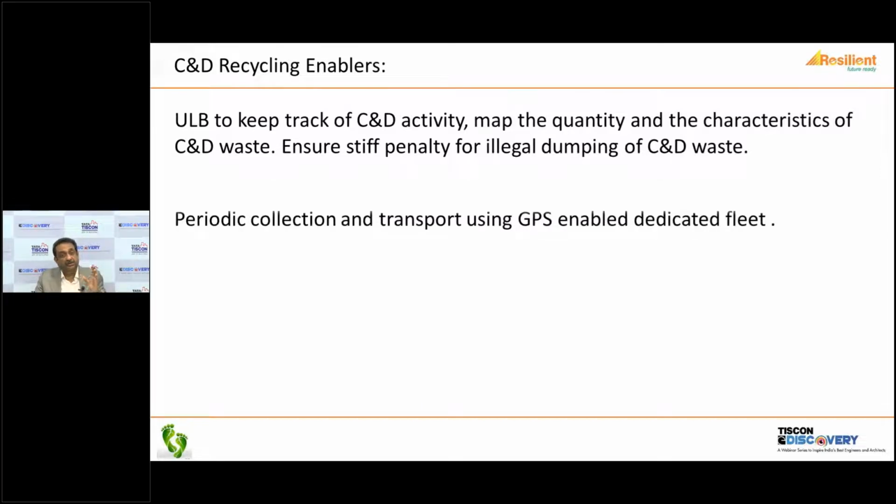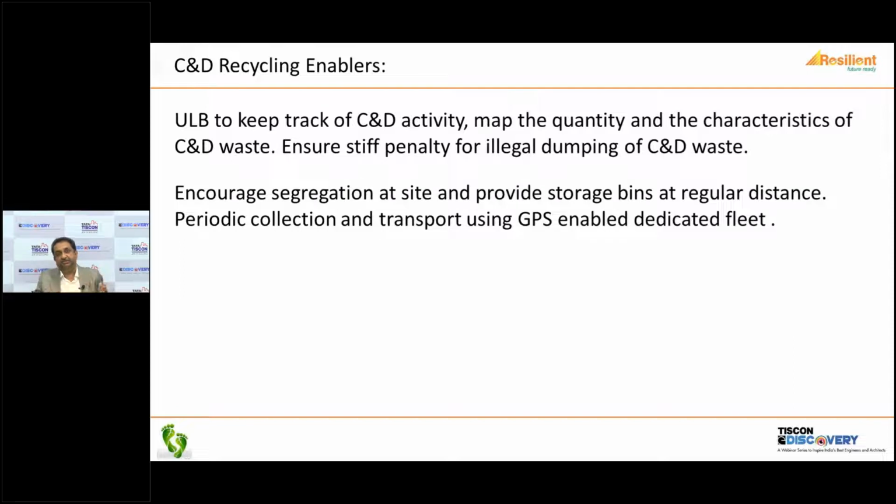You should encourage segregation at the site. We have seen that picture with C&D waste coming with all sorts of things: the cement, the concrete, your mortars, bricks, and gravel. So you should actually try to encourage segregation at the site and provide storage bins at regular distances, so that there is an encouragement for a person to go and deposit this in a place